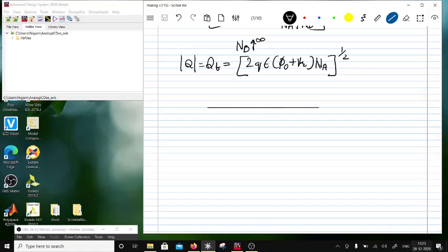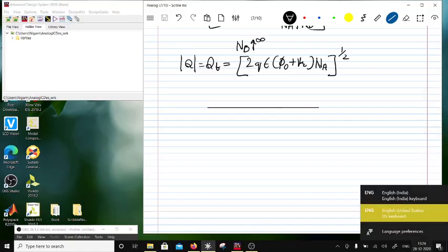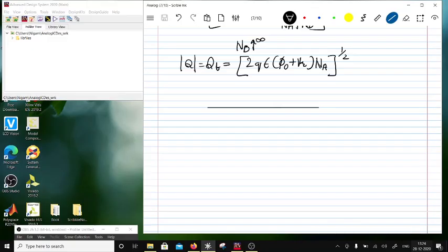Okay, so this MOSFET, this process is an N-well process. So the NMOS device sits directly in the substrate. So when that happens, then what do you have? You have got a gate. The gate is basically polysilicon on silicon dioxide, right? The polysilicon is non-conductive, so you implant the top portion of this, and this becomes a conductive poly. So this forms a gate terminal.